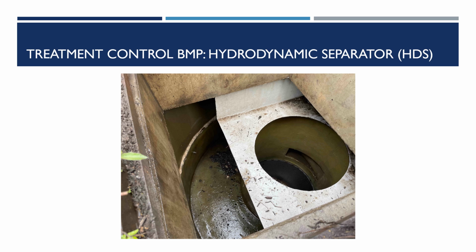HDS units are gravity separators and are essentially wet vaults that use a vortex action to separate coarse sediment and floatables, trash, debris, etc., from stormwater to the surface of the upper chamber using a non-mechanical, non-blocking screen technology. Some models may also remove oil and grease.